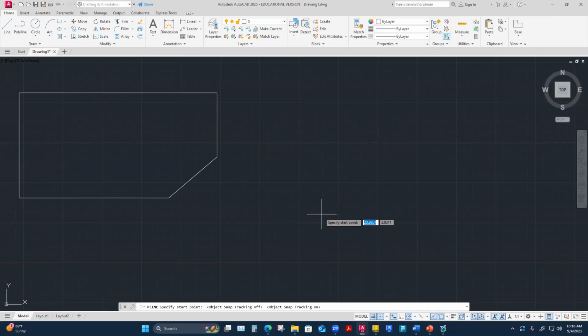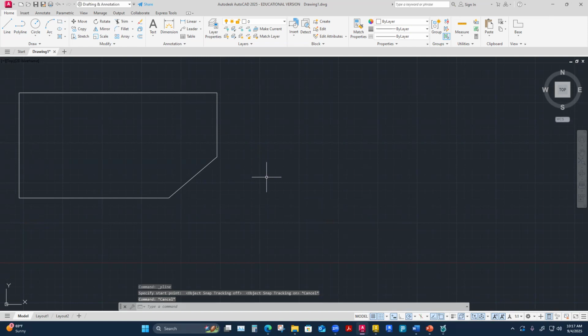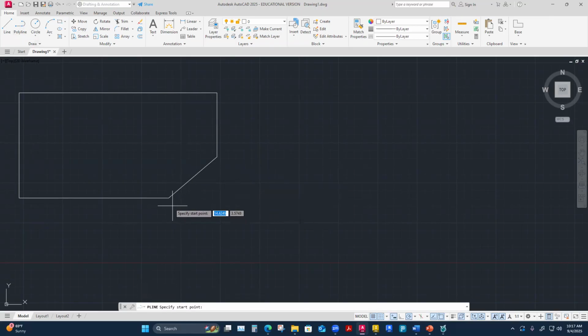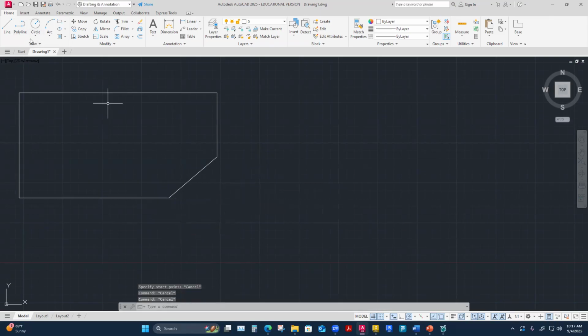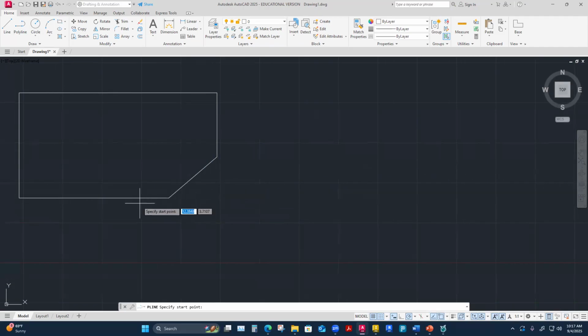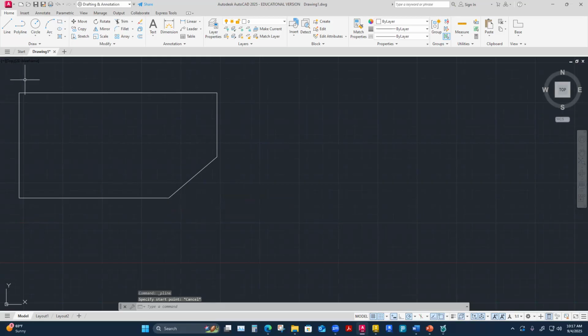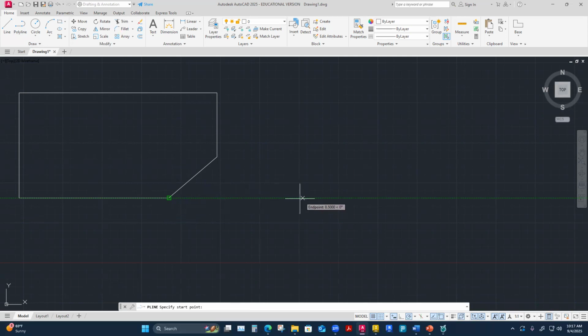So I'm going to draw another shape with a polyline. I don't know what the command is for polyline. Probably PL. PL is polyline for your keyboard command, but it's the same as clicking up here. I'm going to line it up with this, which means I'm going to hover over this and then pull away, and I should get a snap tracking. Yeah, like that. Sometimes if it doesn't do it, I just have to exit the command and re-enter the command, and there it is. Sometimes it won't track, so I escaped and re-entered, and there it shows up.